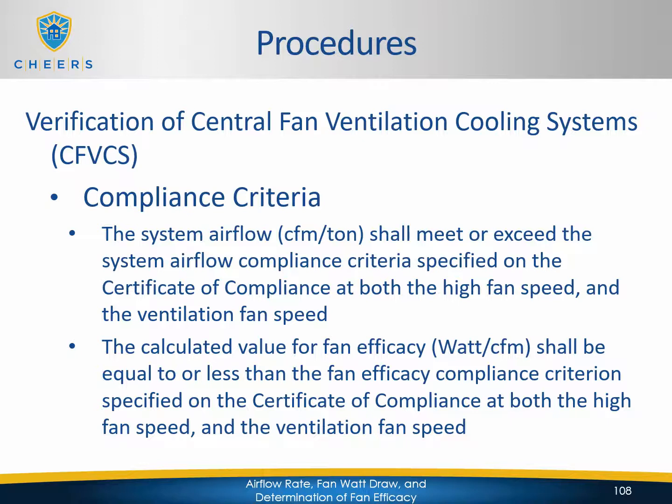So really the only difference for these types of systems is that you're going to be doing the same airflow and fan watt draw test that you did at high fan speed for normal AC systems. You're going to also be doing that a second time, and the second time is going to be just with the ventilation fan speed. So you're going to have two sets of results: one set of airflows for high fan speed, one set for ventilation, and then one set of fan watt draw numbers for high fan speed and one for ventilation fan speed, and these are going to be compared to their corresponding values from the certificate of compliance.